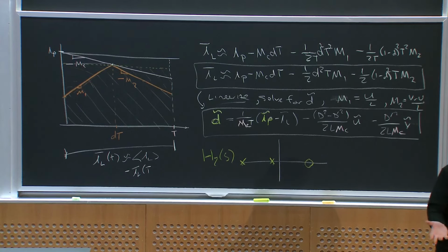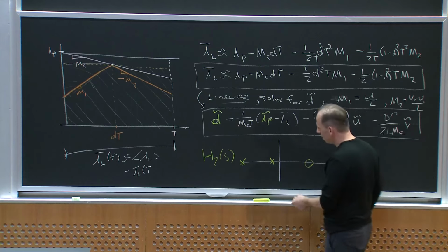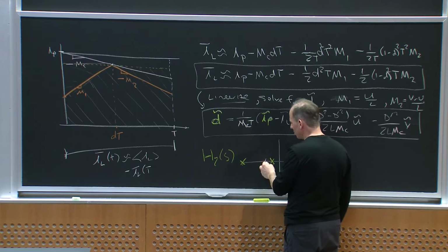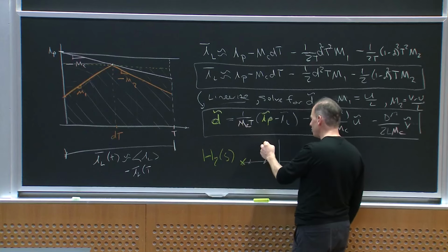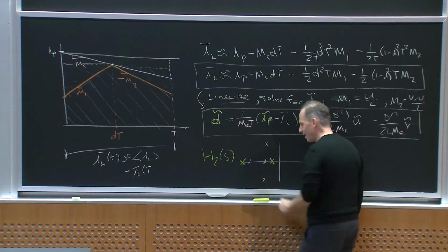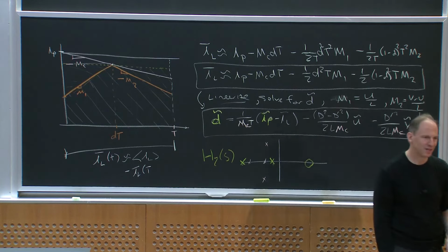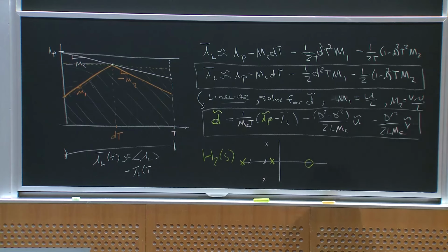As I make MC bigger and bigger, what happens is these open loop poles move, and if I make MC too big, I get undamped poles again. So basically, the higher this value of MC, the closer the converter transfer functions in current mode control look like they do for duty ratio control or voltage mode control.